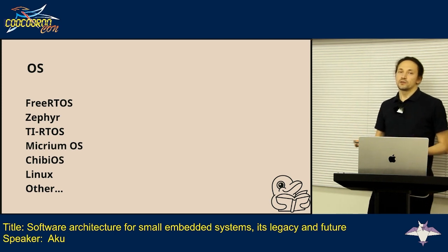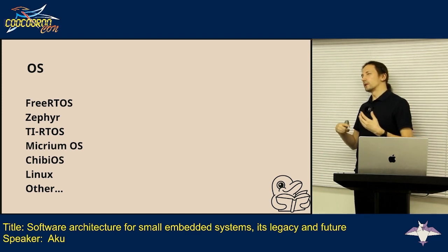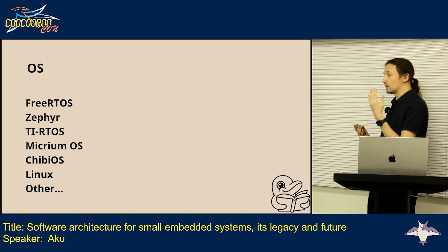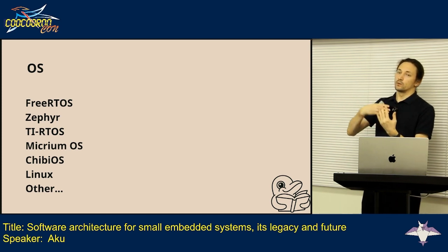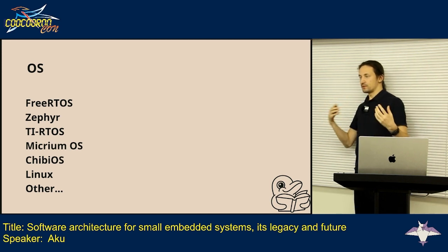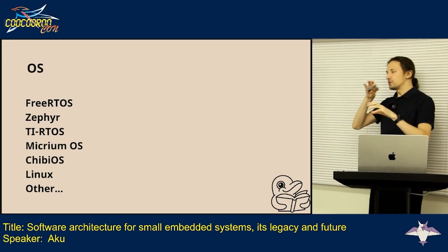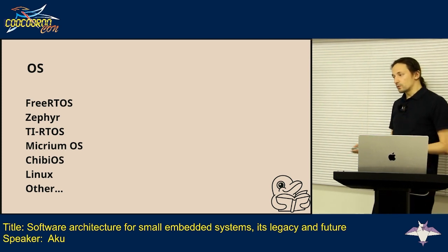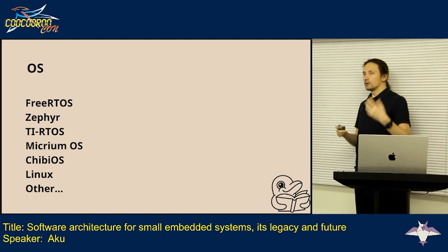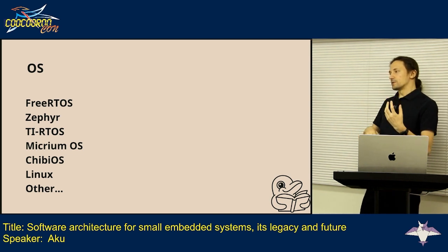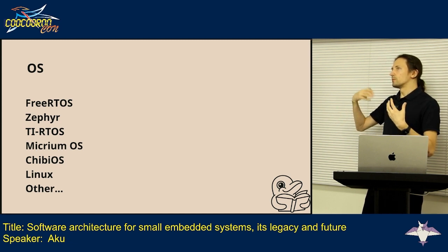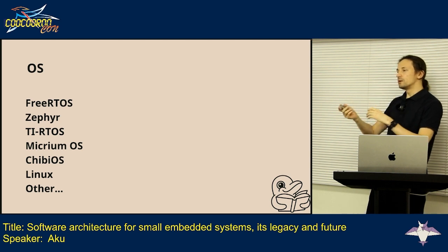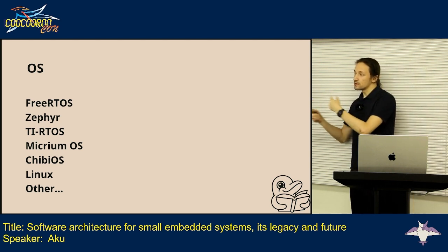By native support, what it means is that when you have one application, you usually need only one stack. And when you have multiple tasks in your application, you would like each task to have its own stack. All older architectures were only able to manipulate one stack, and starting with M cores brought us support for multiple stacks. So you have a main thread, and then you have the ability to do context switches and change stacks on the fly.